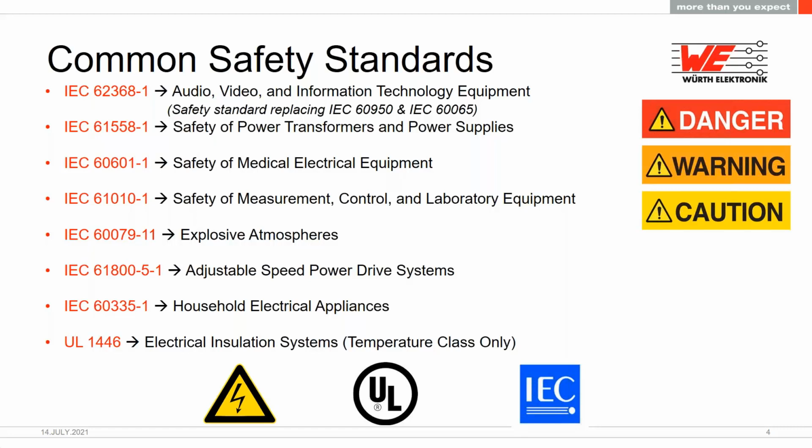The technical committees that are responsible for writing each of these standards often refer back to multiple different base safety standards, if you will. This creates a fair amount of overlap between the various safety standards we design, at least in terms of the transformer construction. But there's also many subtle differences. In some cases, certain wire types are not allowed to touch one another. There might be different requirements for the number of thin sheet insulation, and so on.